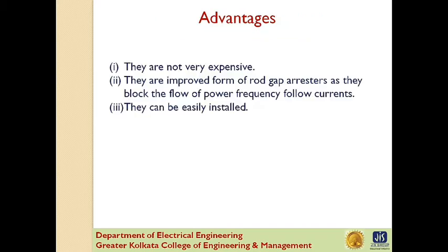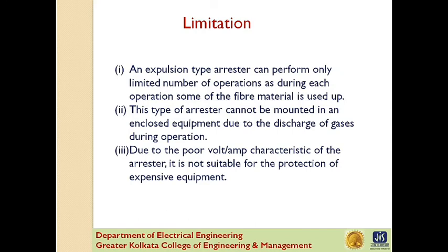The advantages are: they are not very expensive. Second, they are an improved form of rod gap arrester as they block the flow of power frequency follow currents. They can be easily installed. And what are the limitations?